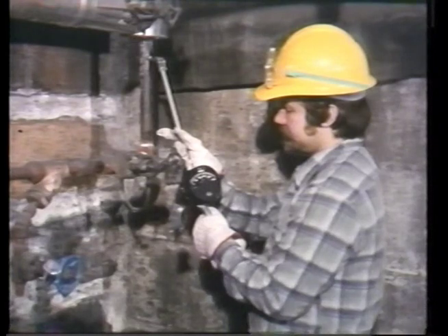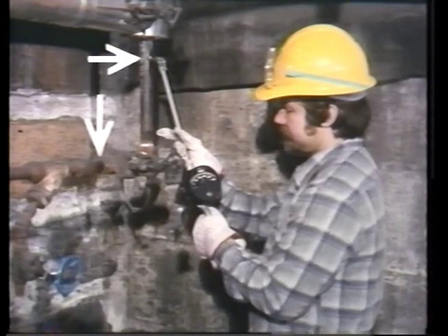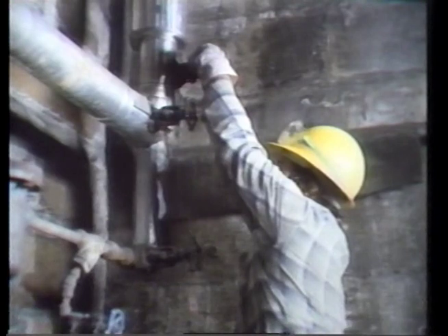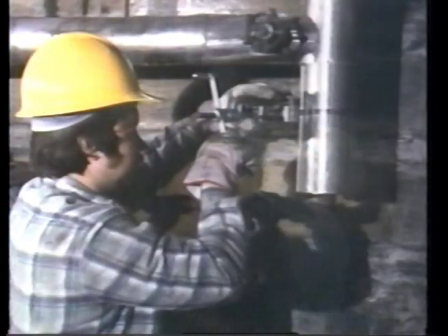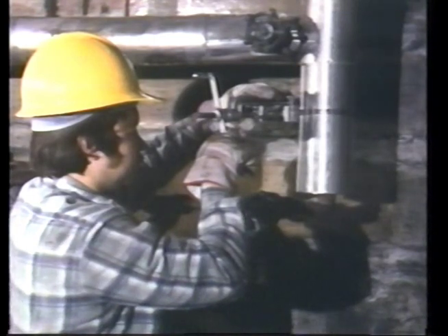If this reading is now within the expected range, there's probably an obstruction between this point and the last place you measured. Be sure to properly isolate the trap system before removing the obstruction. Once it is removed, replace the pipe insulation and return the system to operation.